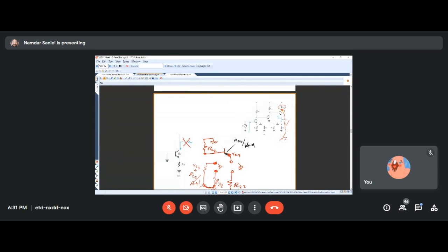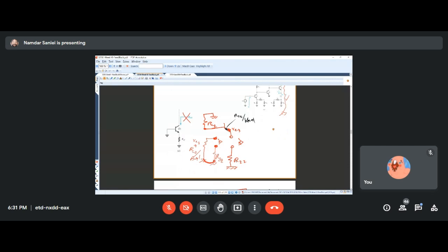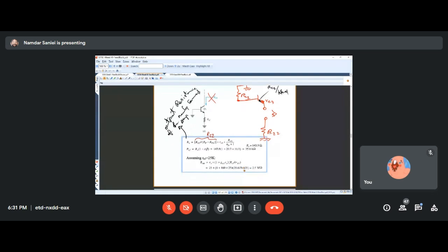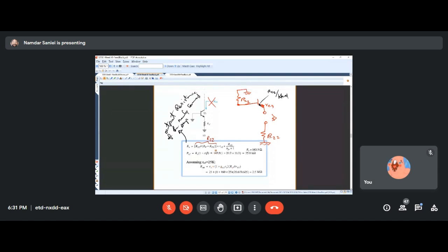So from up there we have RC3 connected to ground as well. The parallel of the two is going to be the smaller one. So we really didn't need to do that. But just to prove to ourselves, we did it, and it was a good practice, an exercise. In fact, we need to be able to find output resistances like this, or the input resistance.